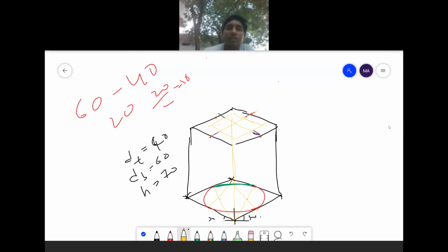So after that, using the 4 center method, I have a center point here, one here, one here, one here. From those points, I am joining from top vertex to here and bottom vertex to here. Understand? Then, using another pencil, I'm joining top vertex to this and bottom vertex to these points.